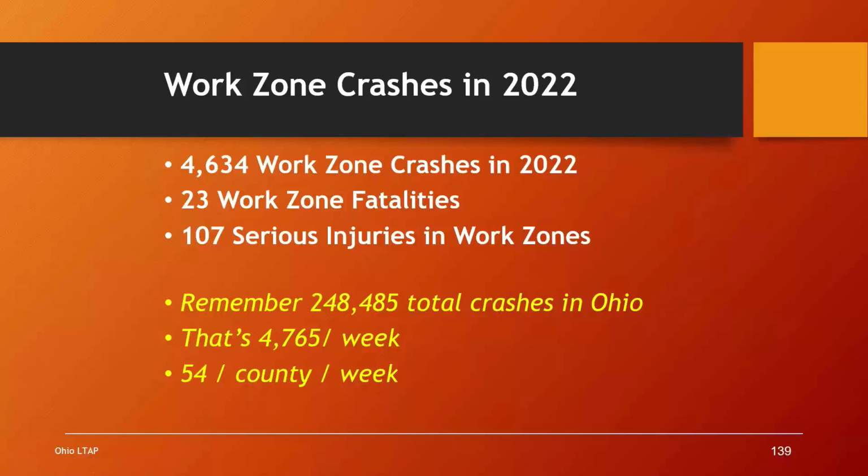I can't stress this enough for our roadway maintenance crews and utility maintenance crews. We don't skimp on the number of signs that are required or the number of cones that you need in the taper or the buffer space, because you're putting yourself in harm's way, but also putting the motorists in harm's way. We want everybody to be safe.